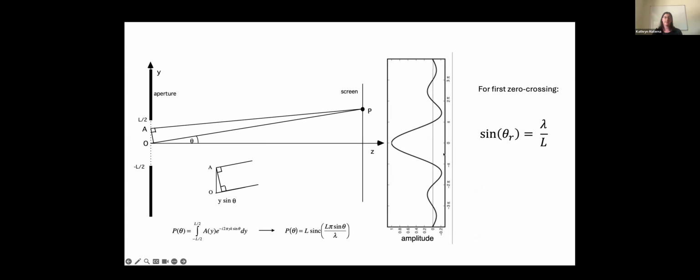The reason this applies to satellite interferometry, or SAR in general, synthetic aperture radar, is that the resolution on the ground, and we're going to talk a lot about the resolution of pixels on the ground today, is given by the area between the two zero crossings. So the resolution of the pixel on the ground depends on the ratio of the wavelength to the size of the aperture.